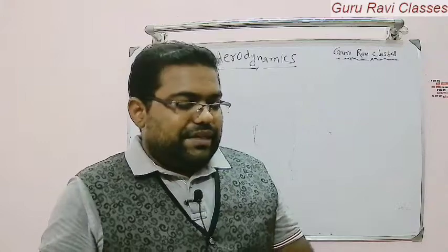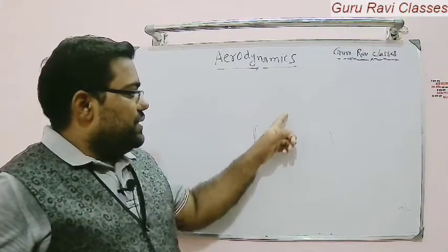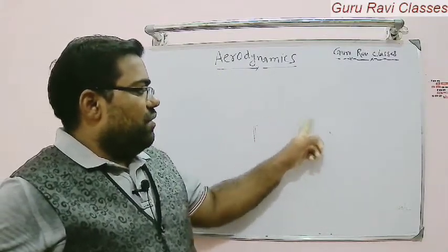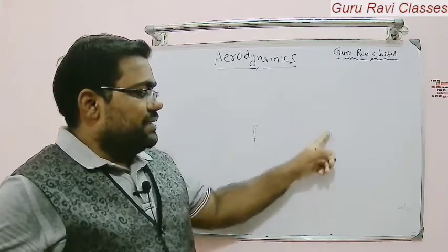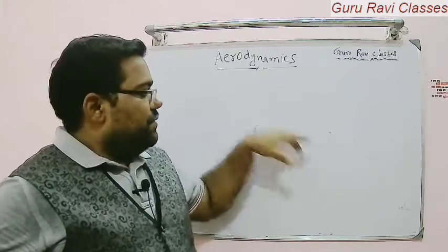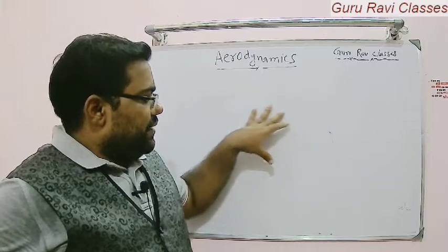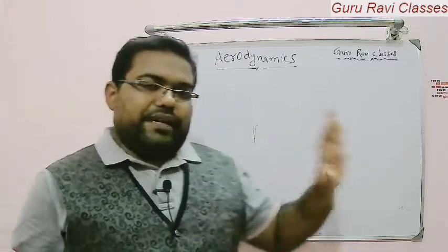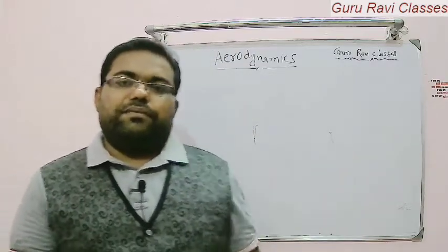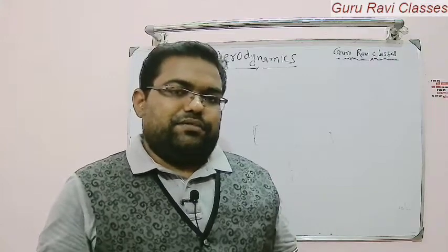So that means the wing which is attached here, and the fuselage is also there, so it will be taking all the things including the fuselage, right? This complete, if you are viewing from the top, we will get one planform like this, and if you are calculating the area of that, that is called wing planform area, that needs to be considered for performance calculation.